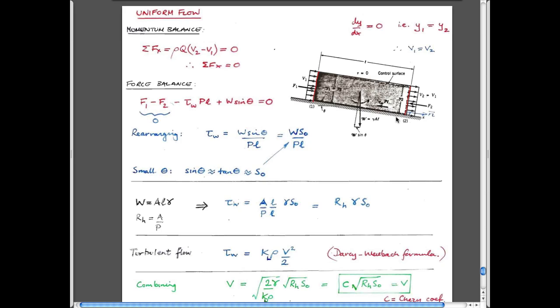We're looking perpendicular to the flow. The flow is in this direction. We can isolate this block of water and look at the forces applied on it. From conservation of momentum, we could resolve in x and y, but it's easier to resolve along the direction of flow, not the horizontal, which we'll call x, and tilt this to.